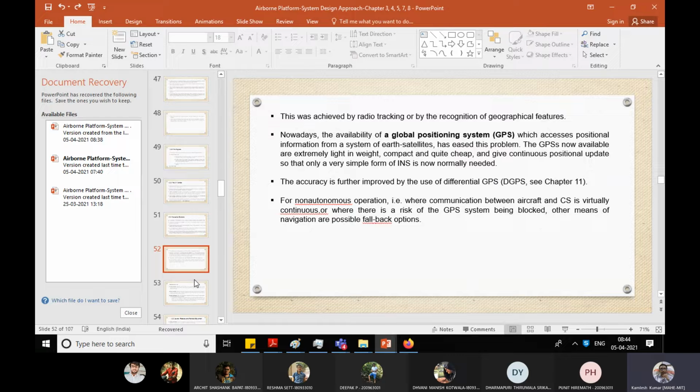So only 4 satellites is enough, but we always want good coverage to make sure that the DOP does not degrade. So this is the idea. If any problem is there, for the DOP you should also have at least a reference frame, like one receiver available on the ground, which is also calculating the same information at the same time.